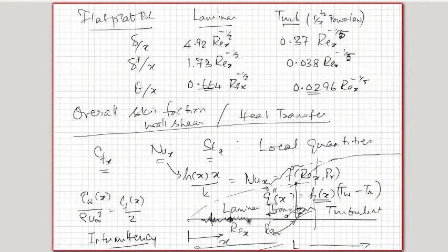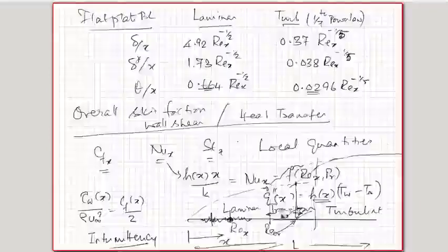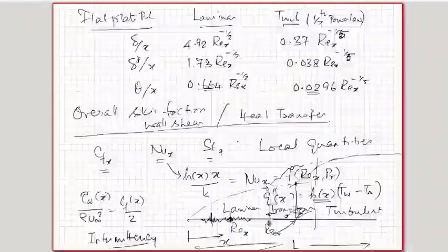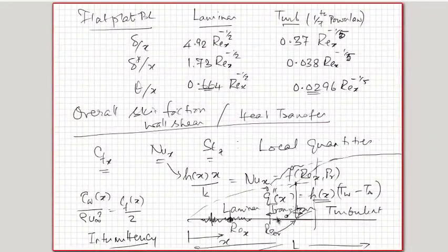In the region where the flow is laminar, these disturbances are controlled because the viscosity overpowers the disturbances and the flow becomes smooth again. But in the transition region, in some places it is able to control, in some places it is not able to control, and in the turbulent region, nowhere any of the disturbances can be controlled by the viscosity, and therefore the flow becomes completely turbulent. So this is basically what actually happens.